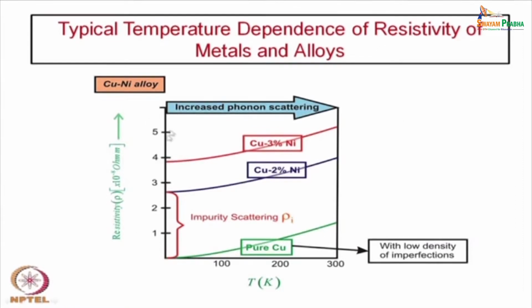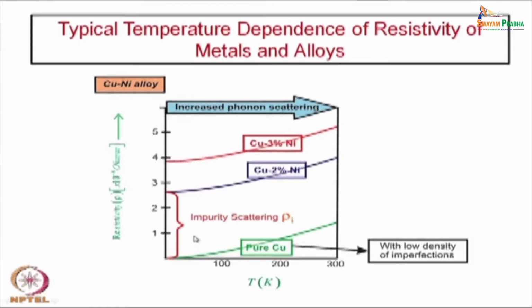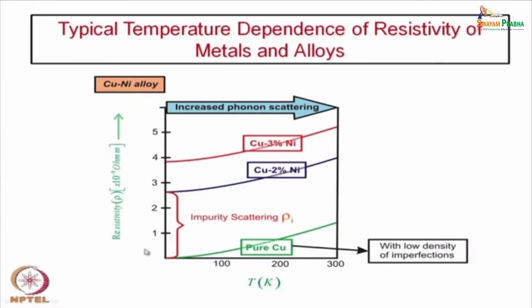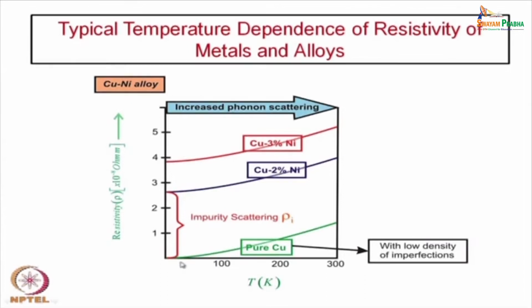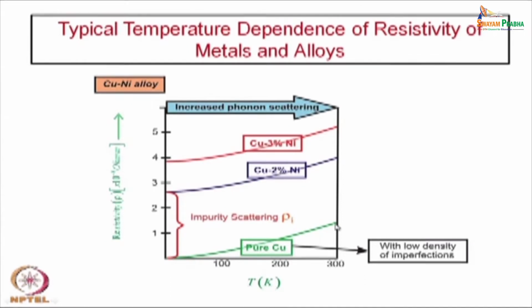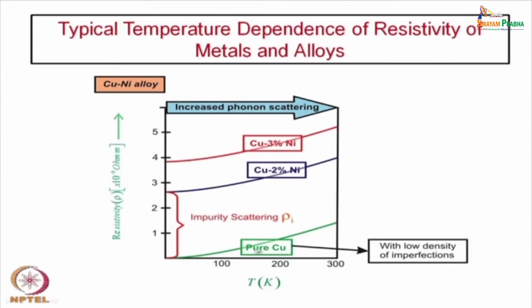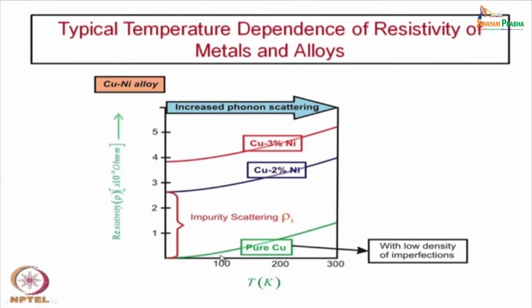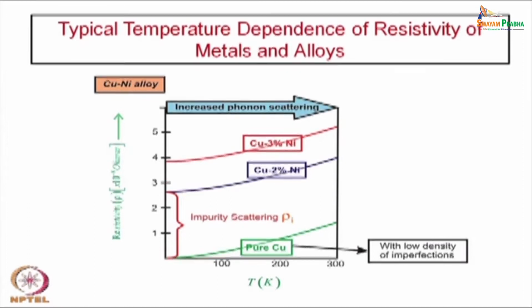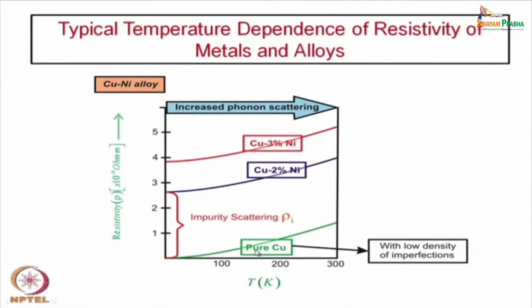This was the experimental parameter I was just mentioning: the resistivity here, of course, not the conductivity, has been plotted as a function of temperature in degrees Kelvin. If you talk about pure copper, which is one of the good conductors, one can see the resistance is increasing as a function of temperature, and it is an almost linear relationship, slightly above room temperature, slightly above 0 degrees Kelvin, very close to 100 degrees Kelvin.